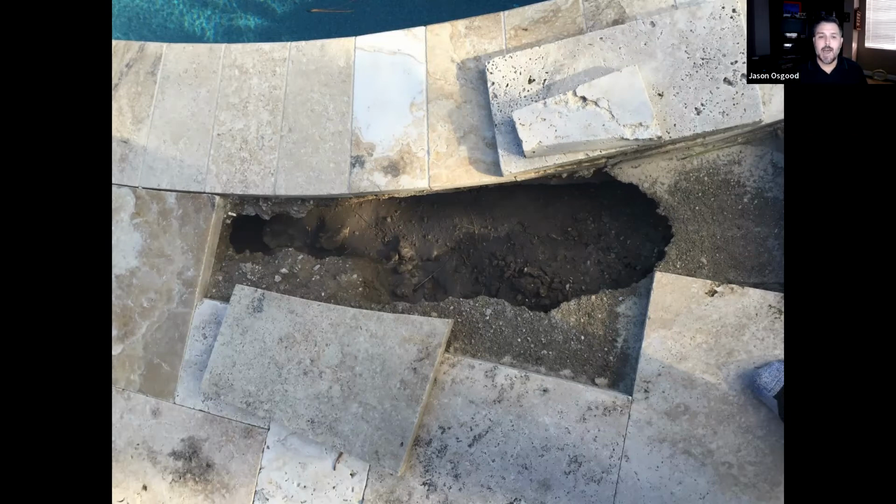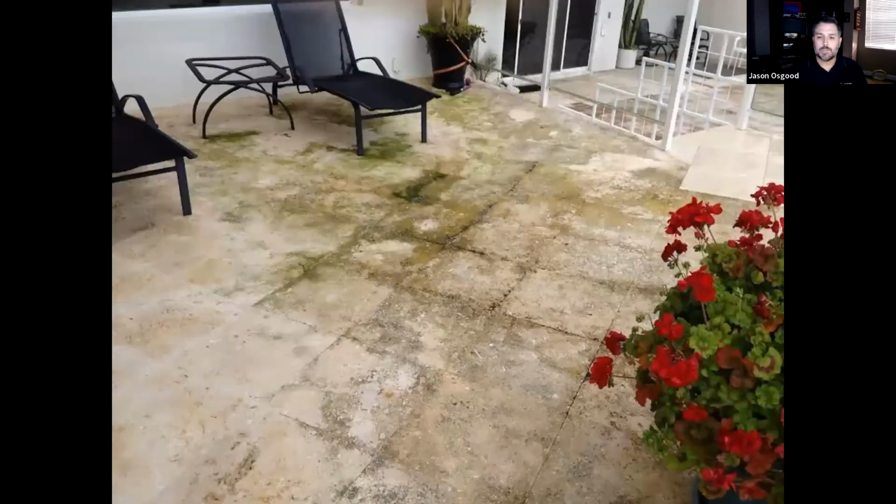The other big issue you're going to have, if you don't do your base correctly, you don't set your pitch properly, is you're going to have an area where water is going to stand, specifically in wet areas like the South and Florida, where it rains constantly. You're going to have a situation where the water is not going to be able to run away from the deck itself. And as you can see here in this picture, right in this spot, is a low area on this deck. This is a very wet area.